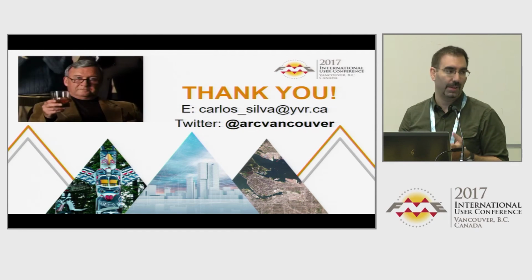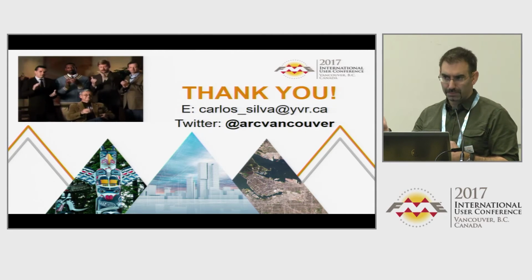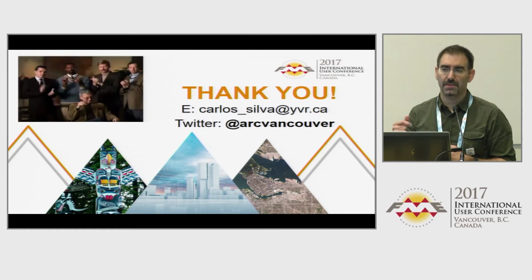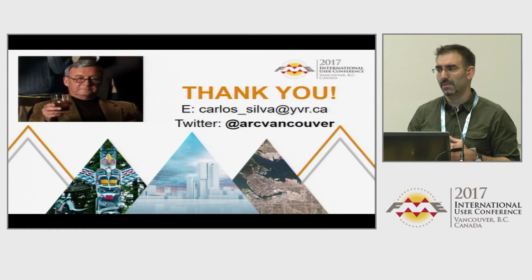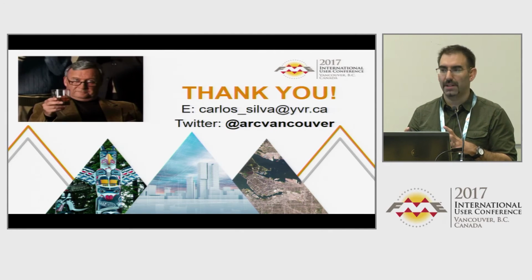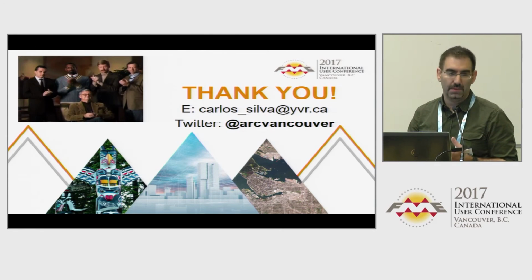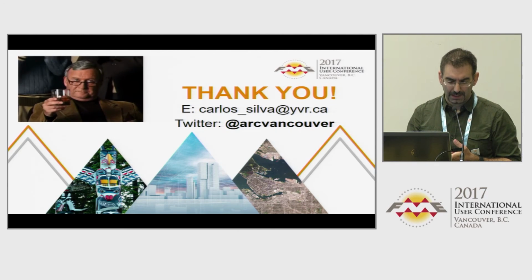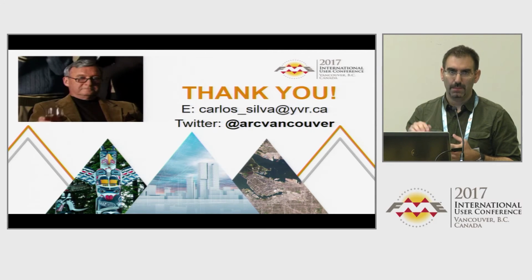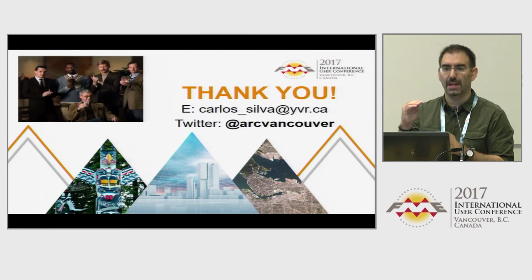But when we get LiDAR, we have it in UTM coordinates. We try to merge it together. I try to generate some contours. We use a DEM. Sometimes we just want to know where the ponding water is, so I'll use a bounding box for specific LiDAR tiles. We'll generate a DEM just for visualization, contours for the CAD folks, and then process the bare earth and non-bare earth LiDAR sets at the same time, just so that we can see the heights of things.